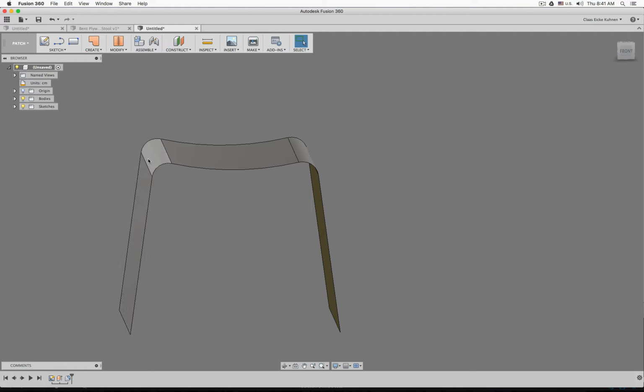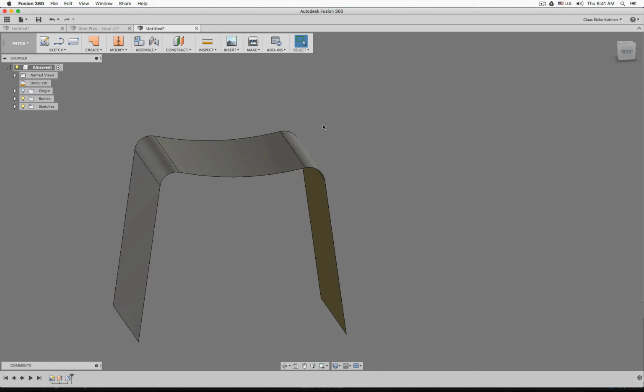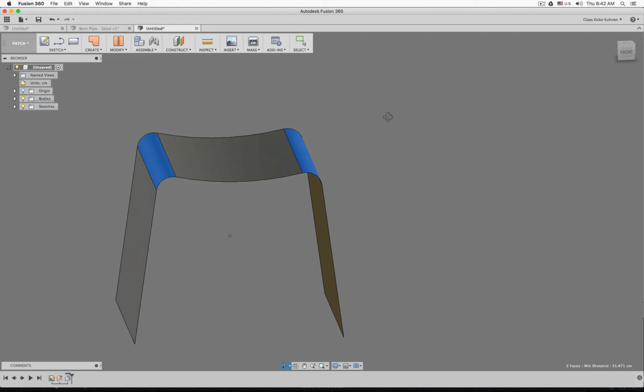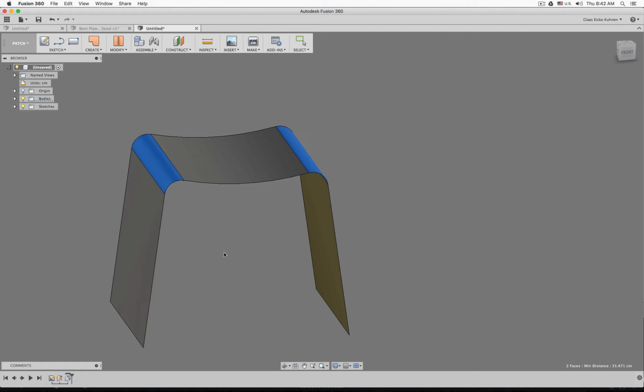but I can still okay the step, because now, as you can see, the fillet command sliced my object into multiple parts. Now what I want to do is get rid of those faces and then add thickness to those, and then we recreate the transition. In terms of technical lingo, these are considered primary surfaces, and this is a secondary surface. So it's more like a transition.